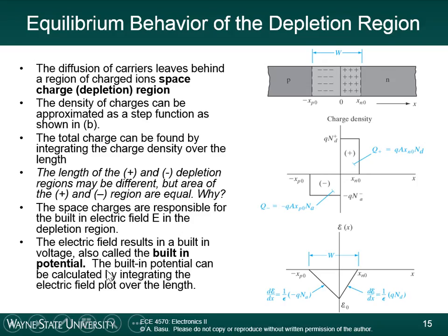We did that at the end of class last time, finding formulas for the total positive charge and total negative charge. Whenever these positive and negative charges are next to one another, this builds up an electric field. The electric field always points from positive to negative, so it is pointing from right to left. We're going to calculate what those specific quantities are.